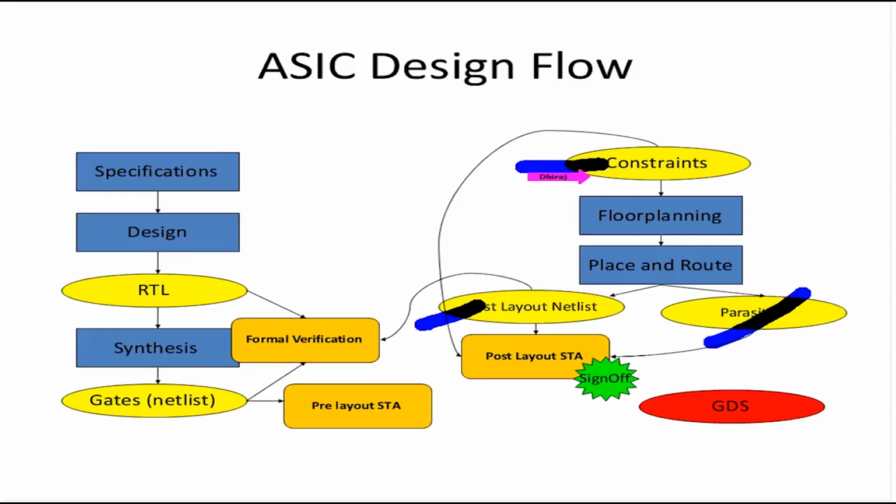Otherwise, any timing result at pre-layout level is not valuable and good enough for sign-off. Sign-off has to be done with complete parasitic data. So the idea of the pre-layout netlist is to clean up the constraints, make sure you have all the exceptions in place, make sure the clock frequencies are correct, make sure that your design does not have big violations, or in fact if it has zero violations of synthesis. So the pre-layout STA will make sure that the synthesis netlist is of good quality.